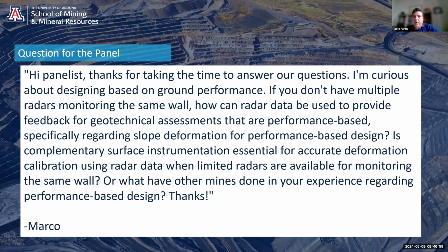We are moving from factor of safety toward a critical limit of strain. Why? Because strain is something you can measure, and it's the first outcome of any numerical modeling, while factor of safety passes through the application of a failure criterion, Mohr-Coulomb or any other. This introduces a lot of uncertainties.